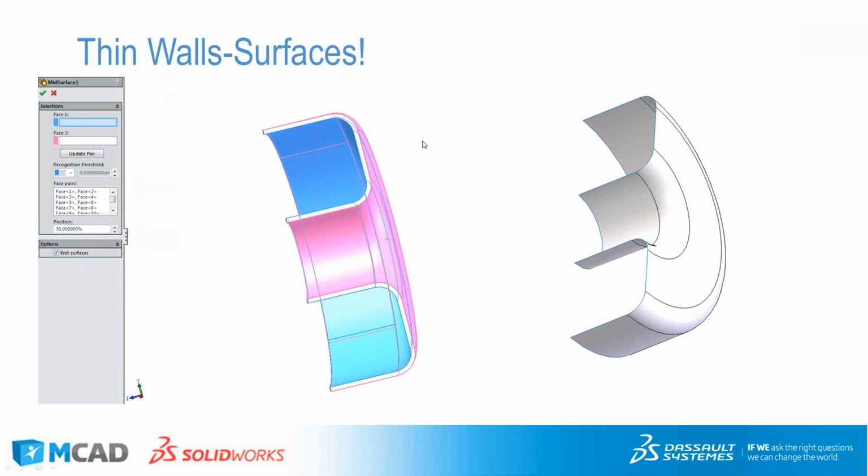mid-surface from. It's a really easy process. It starts with you just go to the mid-surface tool under your surfaces, and as you can see, we've got this update pair button, and if you click that, it'll automatically go and recognize these face pairs and color them purple and blue, find our surfaces, and then we can create our mid-surface, and it'll pop out a surface that looks like this. It's a nice middle of the line, the neutral axis of where our shell would be defined.